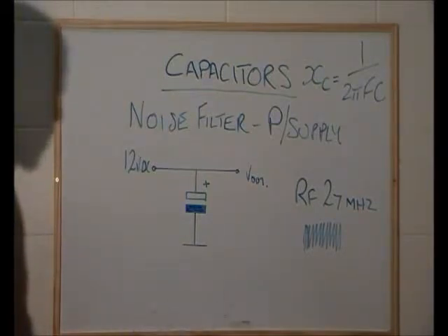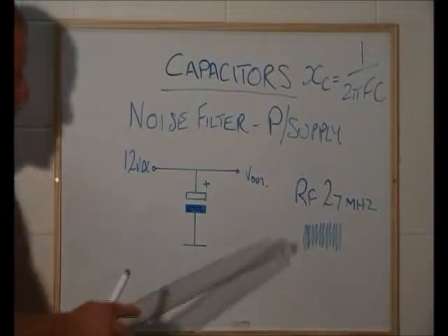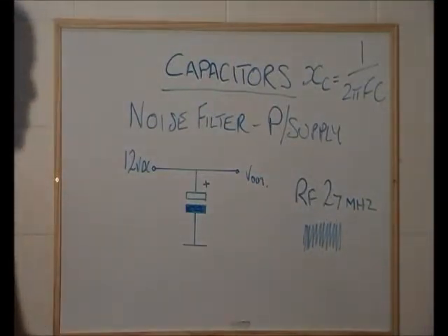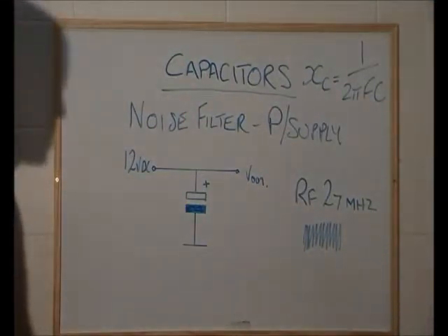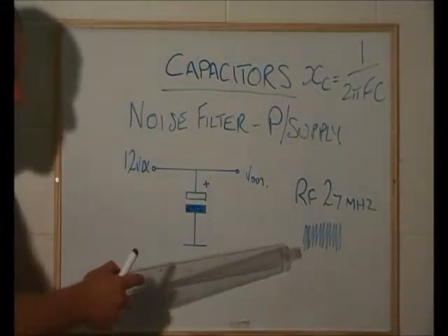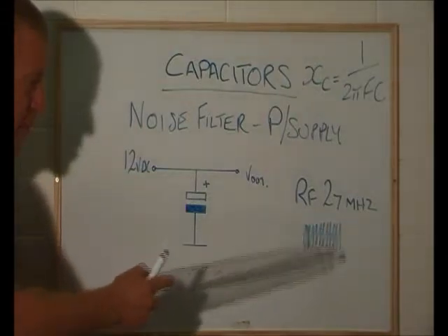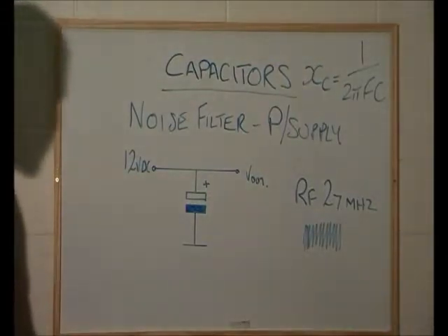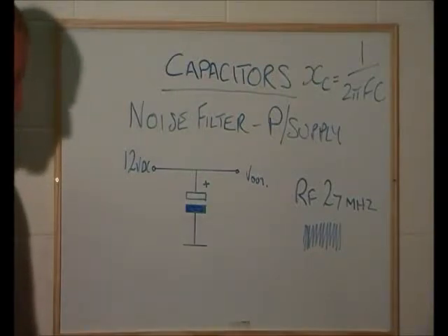So imagine our equipment is sitting in an area where maybe there are transmitters, whether TV or radio transmitters, like the old CB radio operating on 27 megahertz. This used to happen quite often, affecting all sorts of things. We would get a 27 megahertz, 27 million times a second, signal impressed upon our power supply rail.